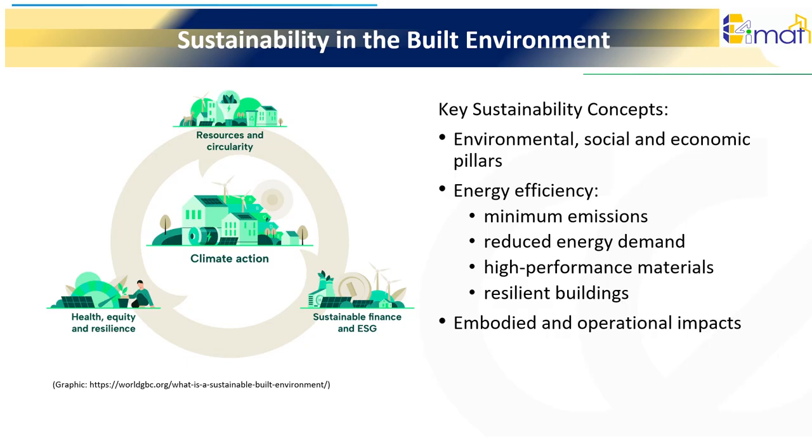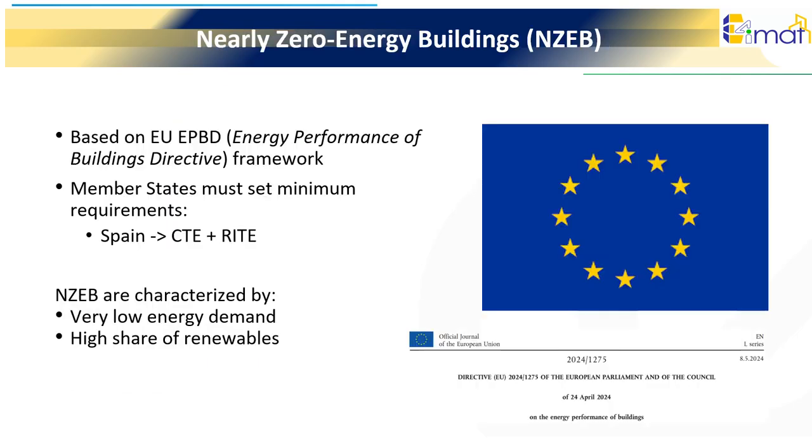In practice, sustainability in buildings means balancing environmental protection, social well-being, and economic viability. It involves minimizing emissions, reducing energy demand, selecting high-performance materials, and designing buildings that remain efficient and resilient throughout their lifespan. In Europe, the concept of nearly zero-energy buildings, often referred to as NZEB, is defined by the Energy Performance of Buildings Directive. Member states must set minimum requirements for energy performance.